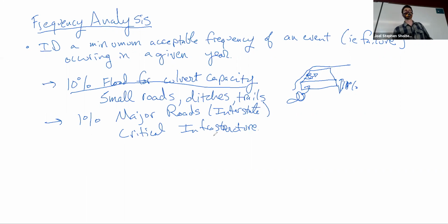There was a flood control dam facility that was constructed off of I-70 in Bosley Wash. You probably saw it under construction over the last couple of years. It's basically a big berm with a gate and an outlet control on it. They designed that to retain, I think, the volume of the hydrograph they synthesized for the 1% flood. So anything that is over that is going to spill out and go downstream through the highway.